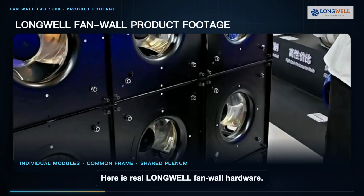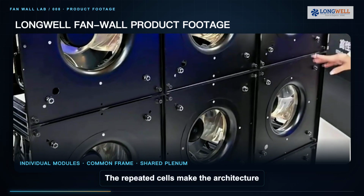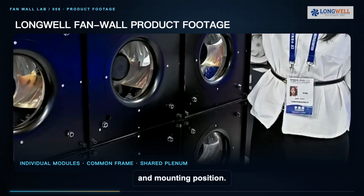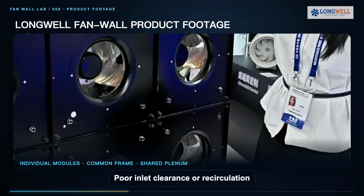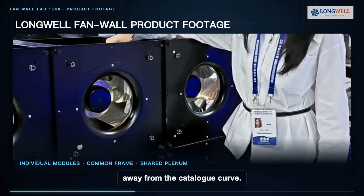Here is real Longwell fan wall hardware. The repeated cells make the architecture easy to see. Each module has its own impeller, motor, inlet geometry, electrical connection, and mounting position. The surrounding frame and plenum are also part of the system. Poor inlet clearance or recirculation between cells can move performance away from the catalog curve.